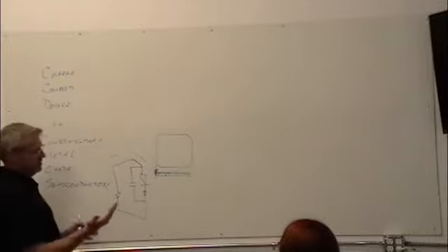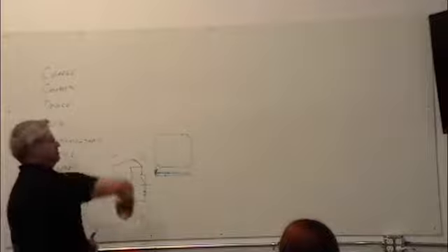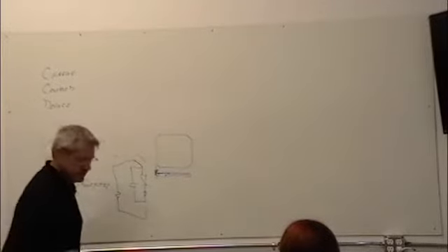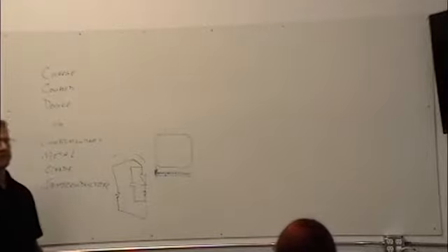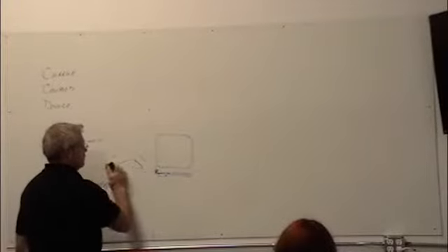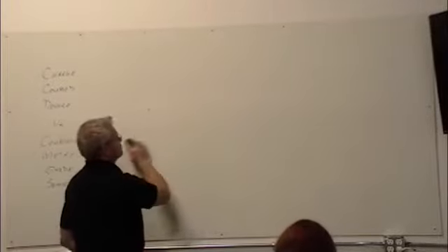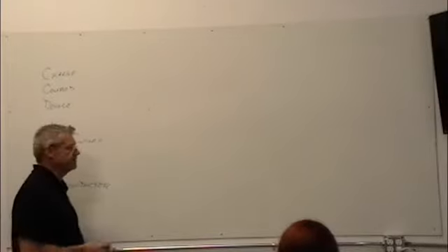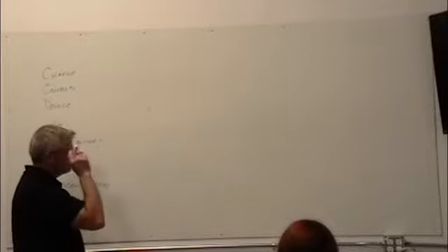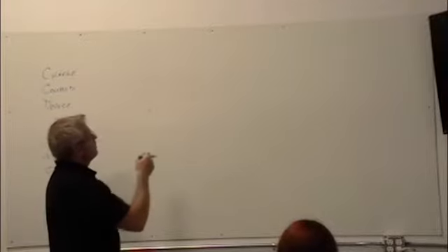And on your solar cell on your roof, I think there's either 45 or 50 of them put in series, and I think it generates about 35 or 40 volts, but there's a whole bunch of them. And each one can do about 5 amps worth of current. It's a series-parallel mix, so they can get about 5 amps, I think, or 10 amps, depending on the cell. So now we go a step further.